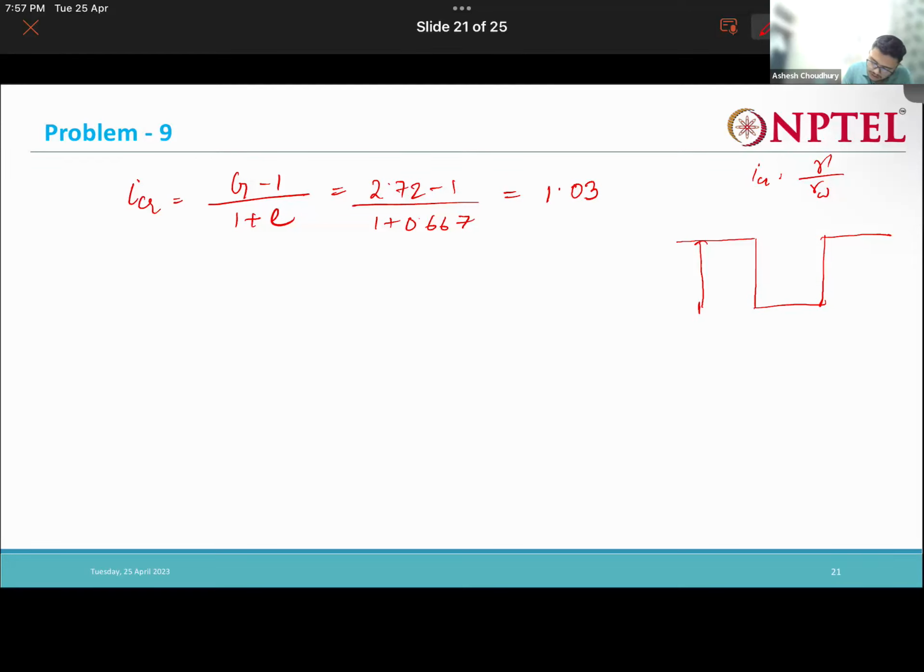Normally, a 1 meter thick layer of saturated clay is drained at both faces. In that case, 15 centimeter settlement takes 2 years. Now what we are doing is introducing one more pervious layer in that soil. Due to that, obviously our consolidation process will get accelerated, isn't it? So for the settlement of 15 centimeter, lesser time should come. We need to find out that new time period.